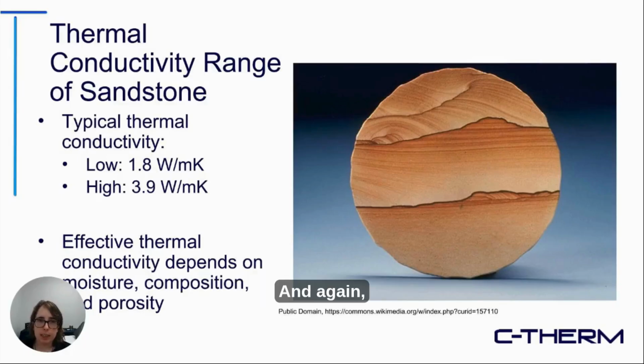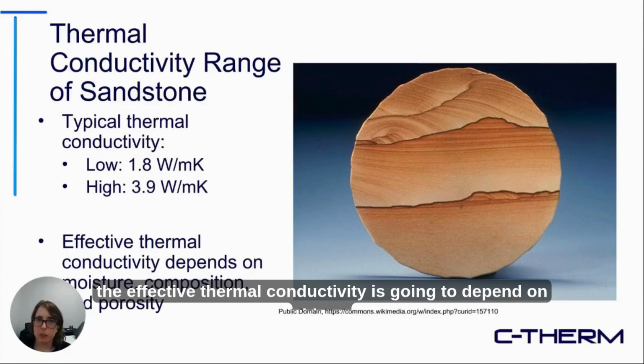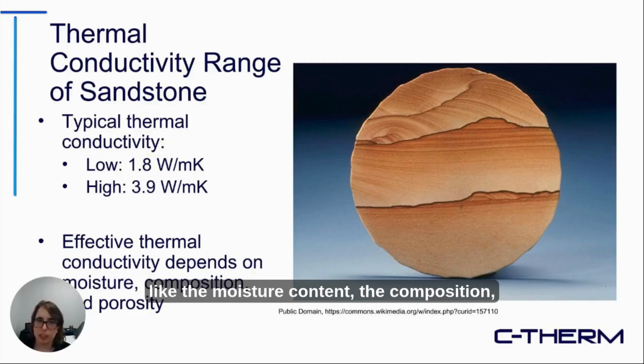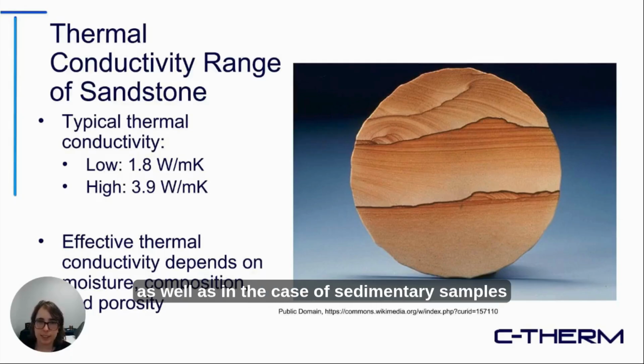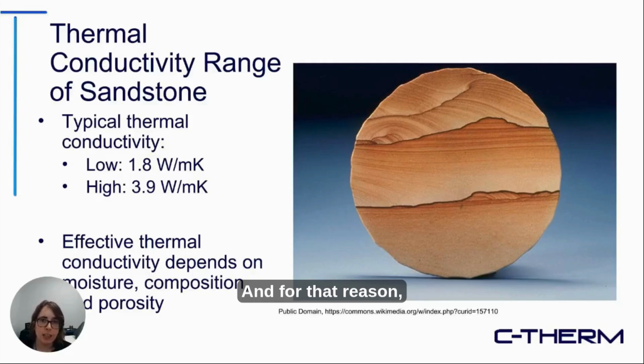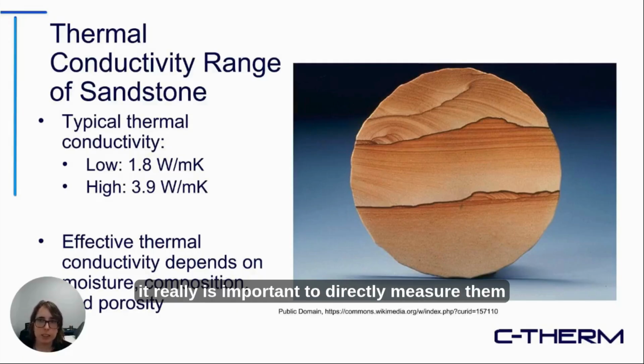Again, the effective thermal conductivity is going to depend on things like the moisture content, the composition, the porosity, as well as, in the case of sedimentary samples like sandstone, how well compacted they are. For that reason, it really is important to directly measure them instead of just taking a book value.